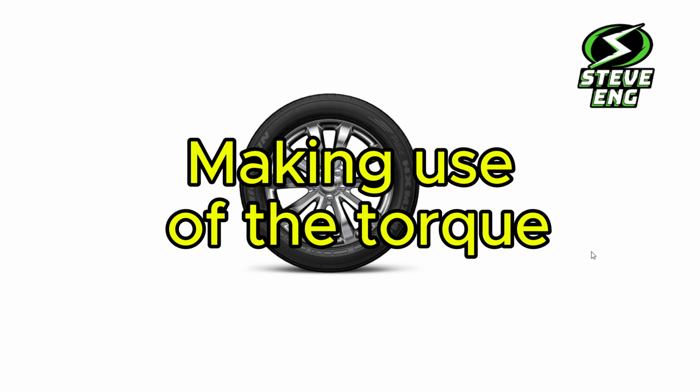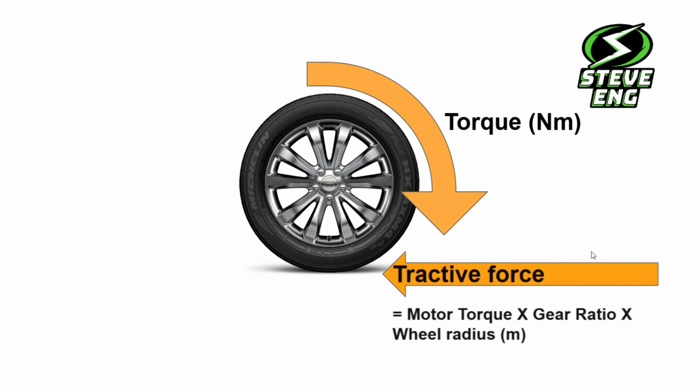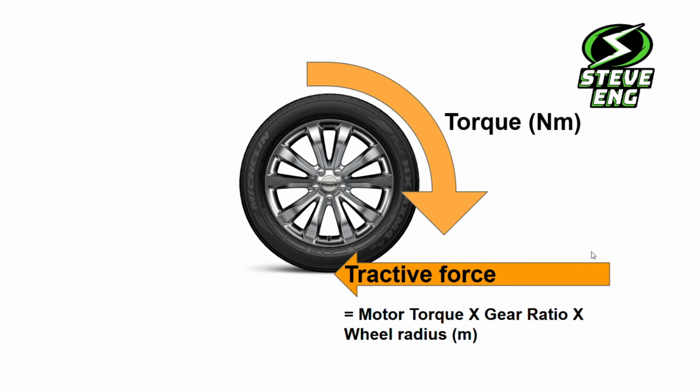This is an extract from one of my previous videos called The Science of Speed. So we're going to apply a torque to our wheel. That generates a tractive force which tries to push the car forwards, and that's equal to motor torque times the gear ratio times the wheel radius. I've got to keep reminding myself to mention the gear ratio because my car doesn't have one, it's just 1 because it's direct drive, but most other people's cars will have a gear ratio, so that's why I'm mentioning it.